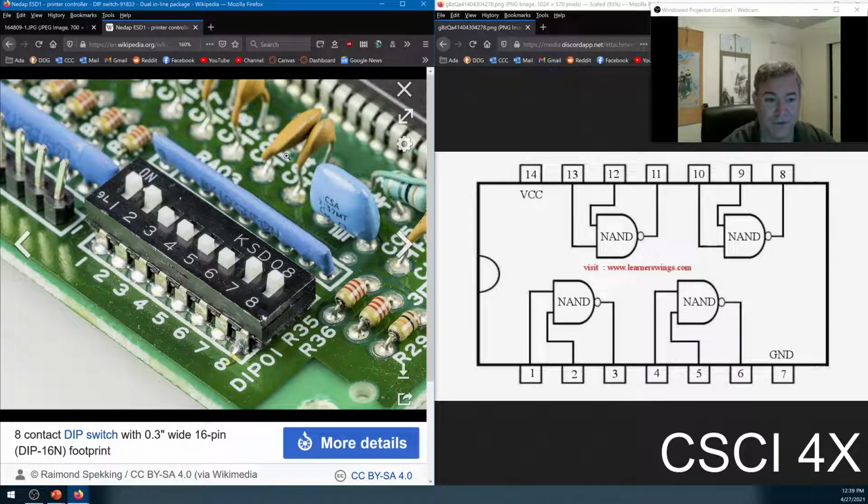It's conductive metal glue. And so if you have a motherboard that just has holes in it, then when you're assembling the board, the first step will come through and just punch in the resistors and the caps and the resistors, and this is a DIP switch here. And there's another DIP chip back over here, maybe it looks like. It'll first stick them all through the holes, and then it will usually do a splash of solder. And the areas that aren't supposed to be soldered might have some sort of coating on them that will cause the solder to just fall off.